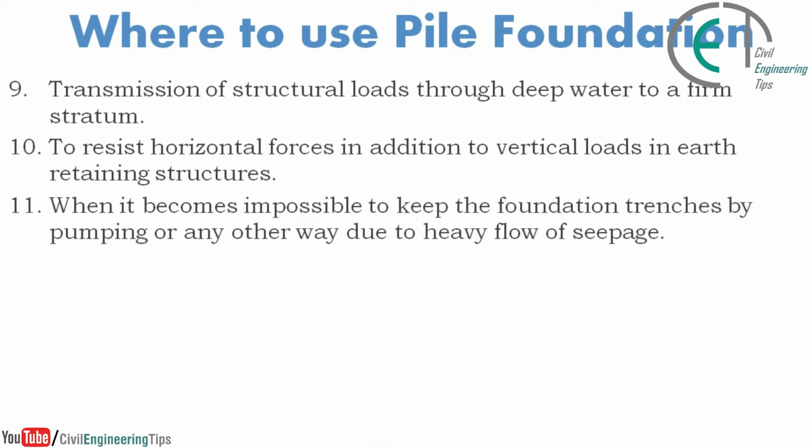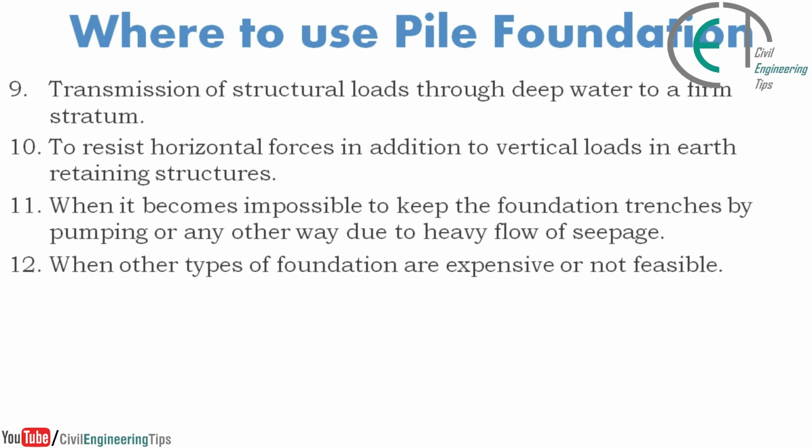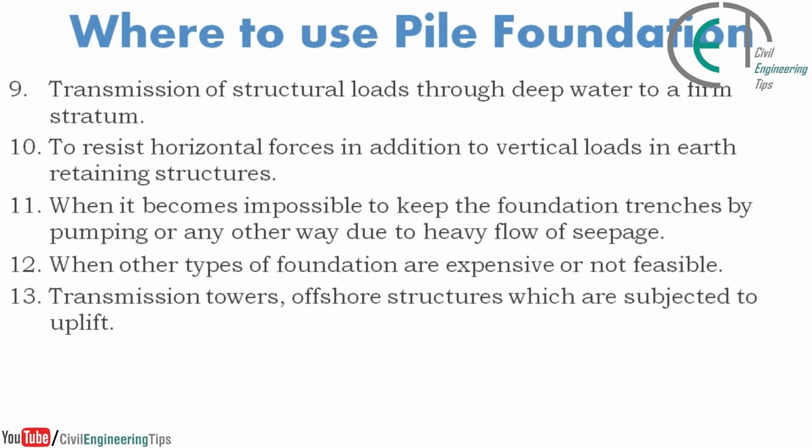When it becomes impossible to keep the foundation trenches dry by pumping or any other way due to heavy flow of seepage. When other types of foundation are expensive or not feasible. Transmission towers and offshore structures which are subjected to uplift.